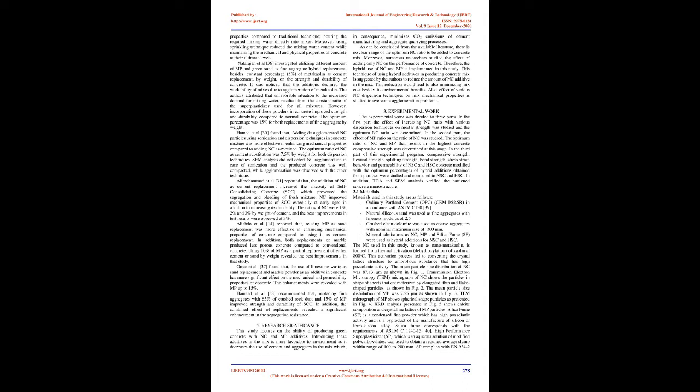Pozzolanic reaction forms additional calcium silicate hydrate, CSH, by consuming calcium hydroxide crystals in hydrated cement, leading to the improvement of cement matrix 16 to 23. While fiber nanomaterials strengthen the cement matrix in tensile strength by acting as bridge connecting both sides of the crack together, preventing crack propagation 24 to 27.